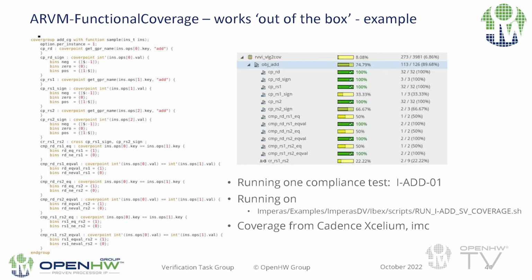That's just an example of it. Of course, it writes out standard SystemVerilog, which should be familiar to a DV engineer. You run it through your EDA company's tools. In this example, Cadence, with their metric tool to show it. And you can see here the coverage that you're getting out of it. So it generates the source and gives you the coverage. You should not have to do it for every design.